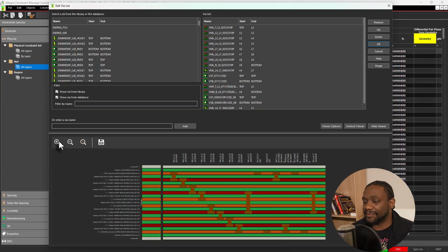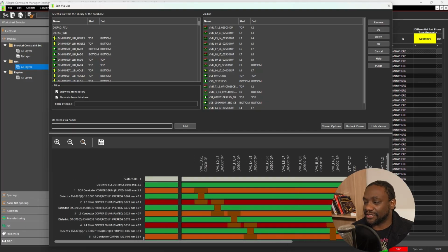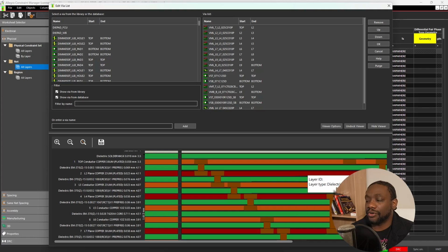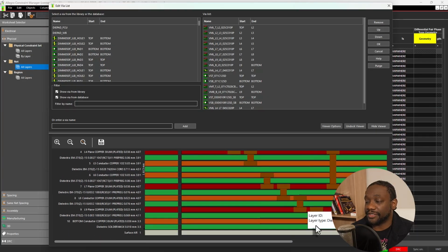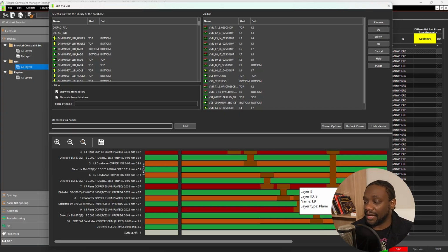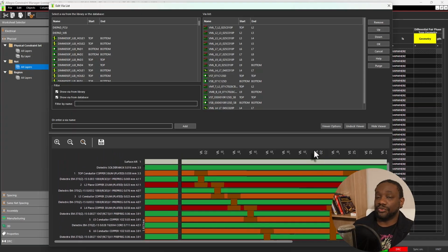Now I'm going to explain these. The via provides you vertical interconnect access. Essentially, it's a trace in the Z direction. Normally, if you're not doing high density boards, you're going to be using a through hole via. The through hole via, which is not shown here, goes all the way from the top layer of copper on your PCB straight through to the bottom layer of copper. So you can see the hole of the via on the top of the board and on the bottom of the board. That type of via is actually the cheapest to manufacture because you could just do one drill hole, stack your PCBs, and you're good.